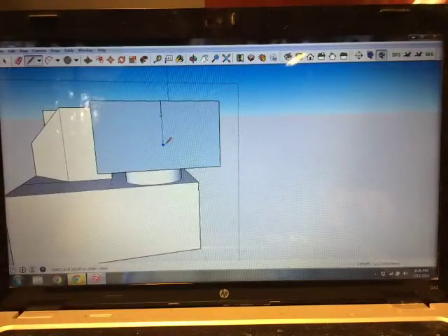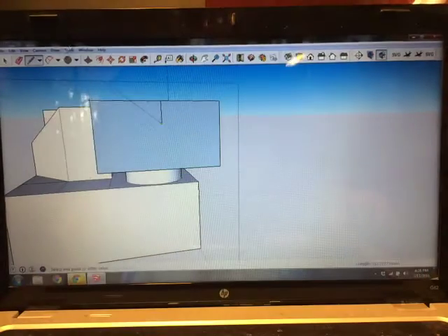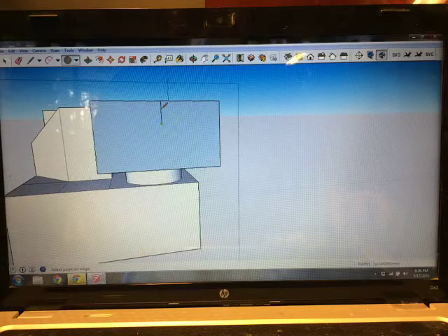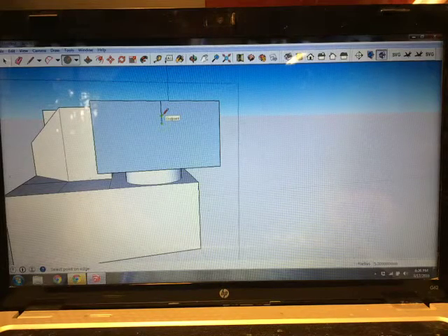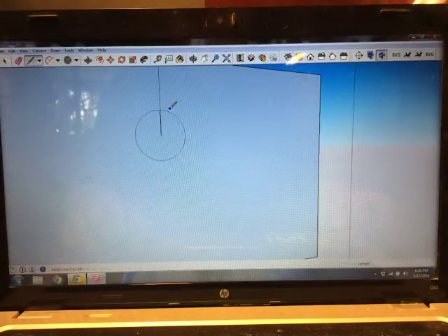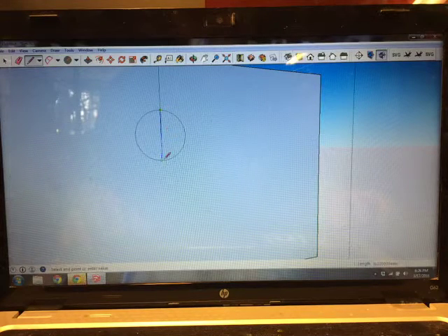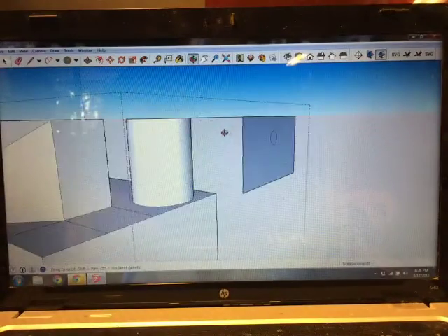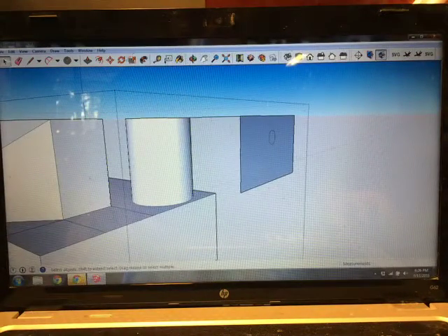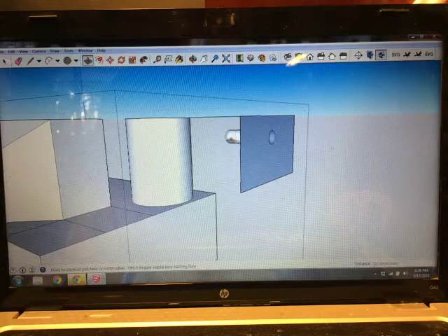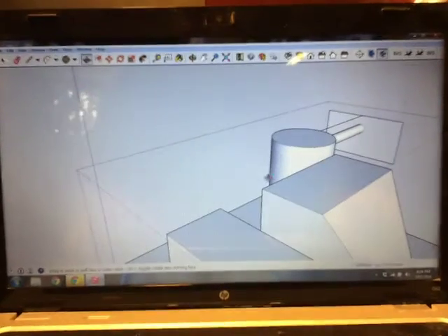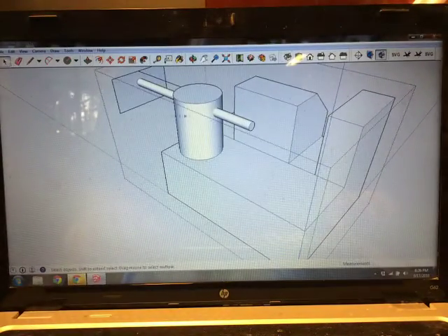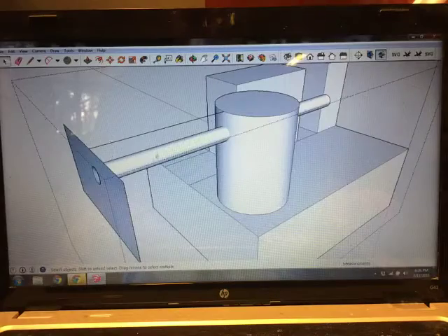And this is just the beginning of how I would perhaps draw a hole that is exactly 10 millimeters below, but the hole is 5 millimeters in radius, 10 in diameter. So I grab the circle tool and draw it up to that 5, and I can double check that, but this should be 5. That's 10. And then I would delete those lines. The next thing I would do would be to use the push-pull tool, and it just travels right through it, right? Well, this is the beginning of it. It's not too complex, and the bigger you design these, typically the better.